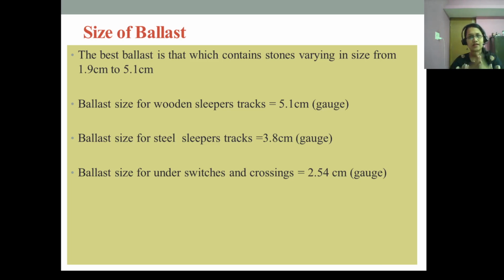So broken stone satisfies all the specifications and requirements of a good ballast. The best stone for ballast is non-porous, hard, and angular, which does not flake when broken. Igneous rocks such as hard trap, quartzite and granite make excellent ballast and are used in large quantities on high-speed tracks in India. Where such hard stone is not available, sandstone and limestone, which make fairly good ballast, are used.